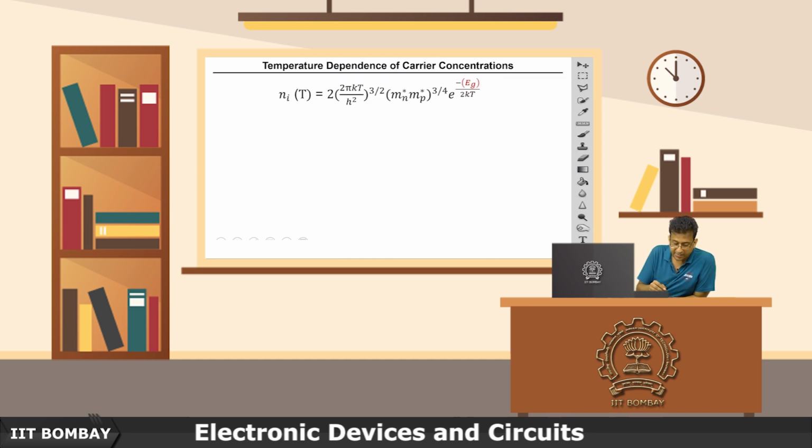So Ni, the intrinsic charge carrier concentration, is what we derived in the last lecture. It depends on the effective masses of electrons and holes, it depends on the energy band gap, and it does depend on the temperature, but it has no dependence on the doping.